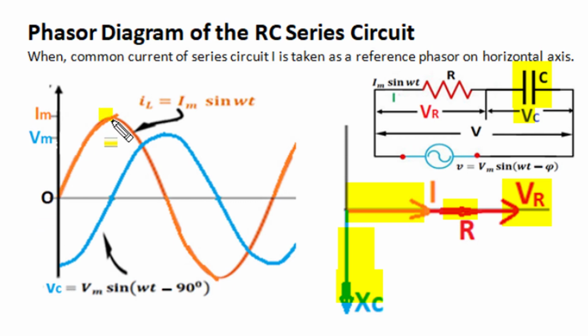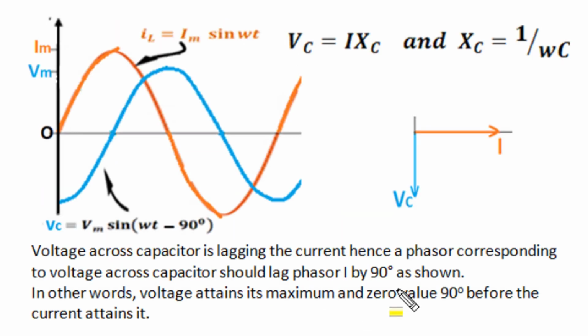as shown in this wave diagram also. That means the current peak will occur before the positive peak of the capacitor voltage, and every identical phase instant of current leads the similar phase condition of voltage by 90 degrees. So the RMS voltage of the capacitor lags the capacitor current by 90 degrees, and RMS voltage and RMS current have a relation. Capacitor voltage is RMS current multiplied by XC, or capacitive reactance, and for omega radian per second angular frequency, a C farad capacitor has capacitive reactance XC as 1 over omega C.